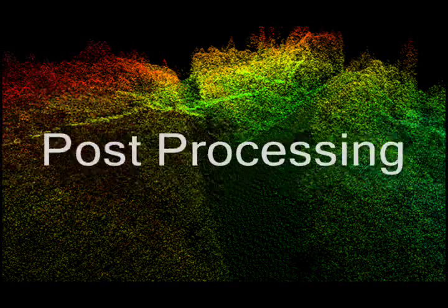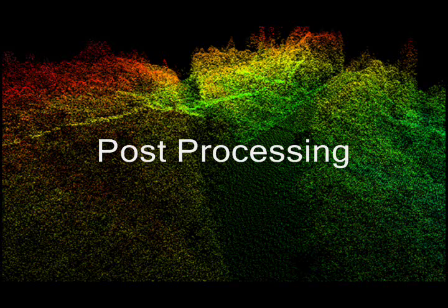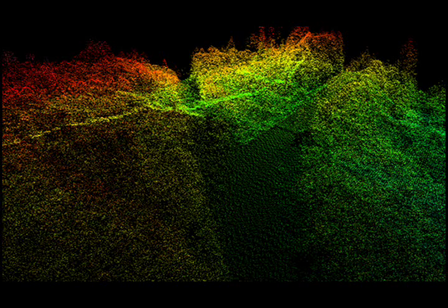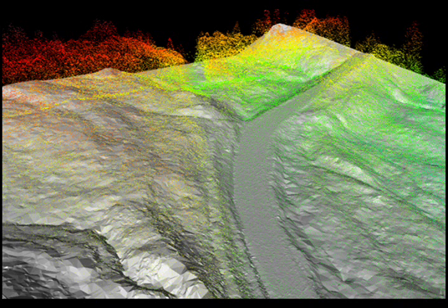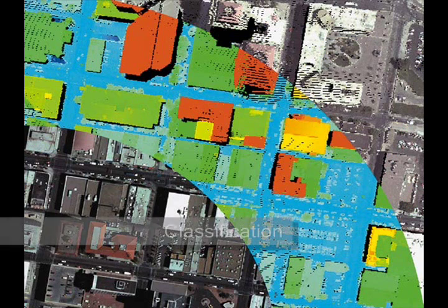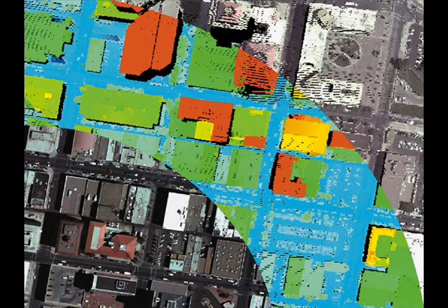However, once collected, various types of post-processing are usually performed on the point cloud to make the data more useful to specific applications. Processed products or deliverables will vary by application, but some common ones include further classification of the point cloud, such as subsetting first and last returns, and more refined classification, such as the objects from which the return reflected, for example, buildings, asphalt, or vegetation.